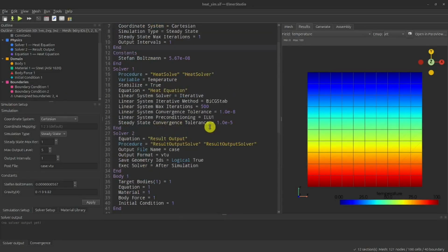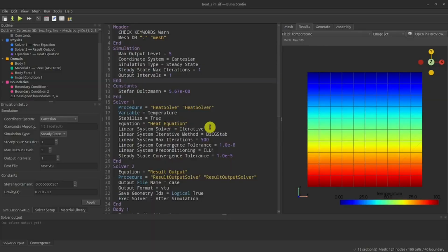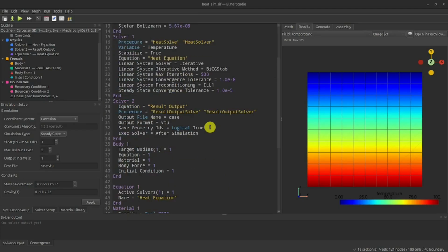One thing worth flagging up front: the SIF format isn't formally specified, so there's no published grammar or standards document. It's grown organically since the mid-1990s. And the de facto reference is the ElmerSolver manual published by CSC. So when we walk through this file, I'll be referencing that manual, and at the end I'll point you to it.